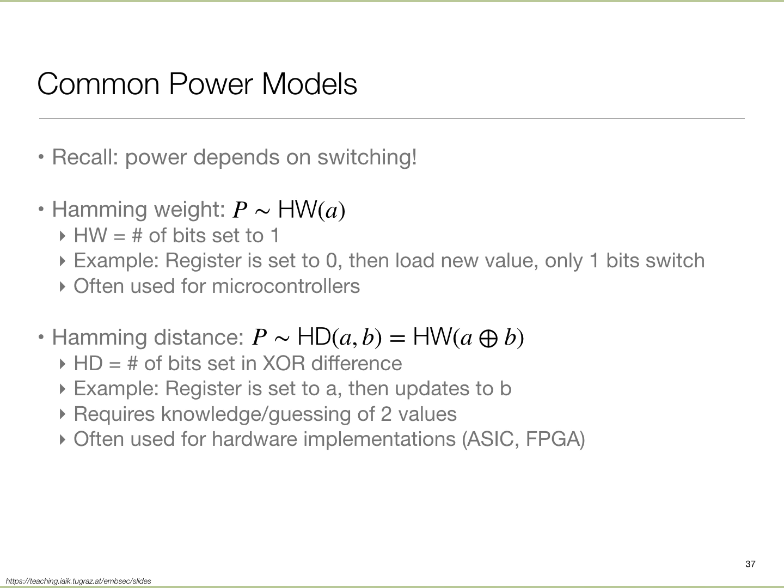So it kind of goes back to the idea I said earlier on, which is to do it for both 0 and 1. What happens in CMOS, the way I showed it, is that there was an asymmetry. For some inputs the bottom side is on, for some inputs the upper side is on, right? There's a class of logic with four paths: two upper paths and two bottom paths, and always one upper path and one lower path are on. So the circuit, irrespective of the input it is seeing, always consumes the same amount of power.